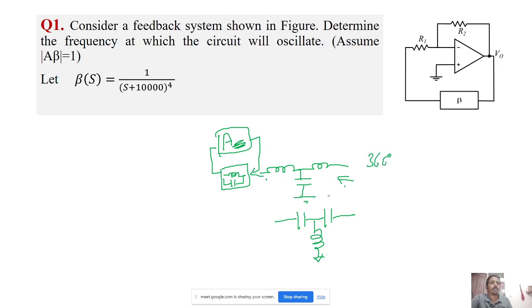So these are high frequency oscillators. In high frequency oscillators we use inductors and capacitors as tank circuit, and that will lead to such frequency. This is known as Hartley oscillator, and this is known as Colpitts oscillator. It depends upon which format we use, whether 2 inductors and a capacitor, or 2 capacitors and an inductor in feedback. So there are such oscillators also.